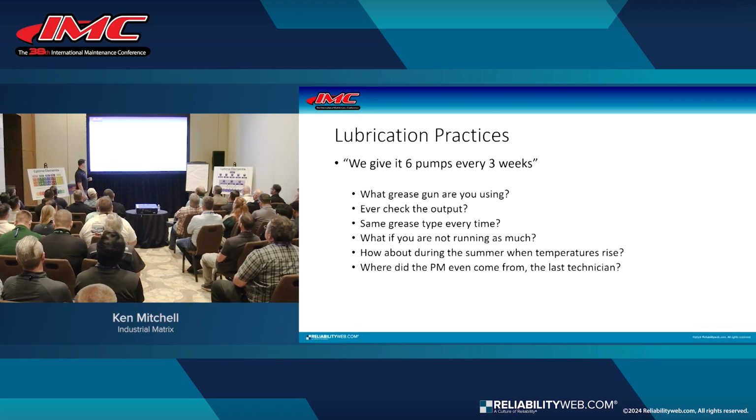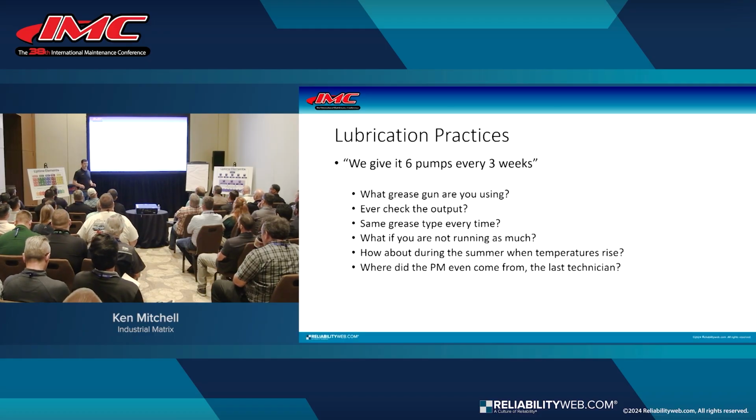We really got to look at our practices. Are we using the same grease every time? What if you're not running as much? How about during the summer, the winter, temperatures rise, temperatures change? Does that work order, does that PM stay the same? Or are we modifying that depending on the seasonal, the demand of the machine, the output, and the wear?